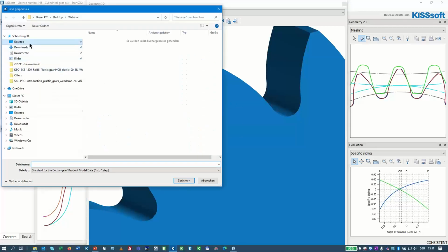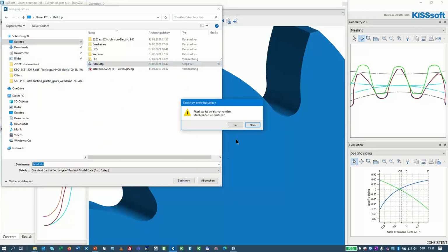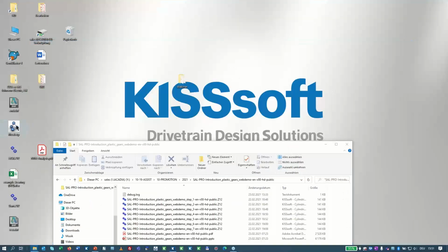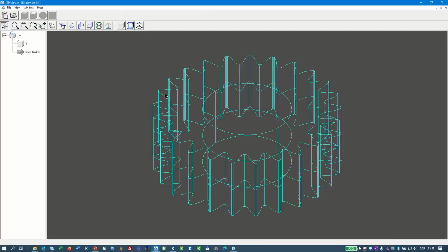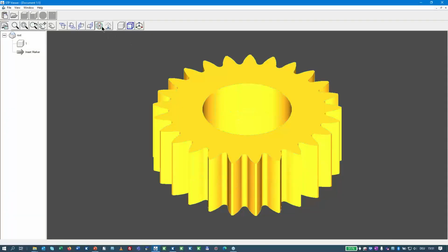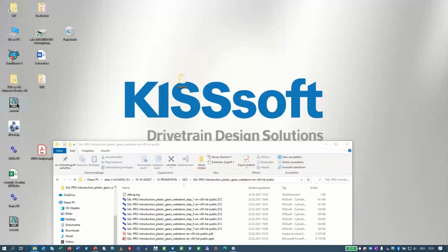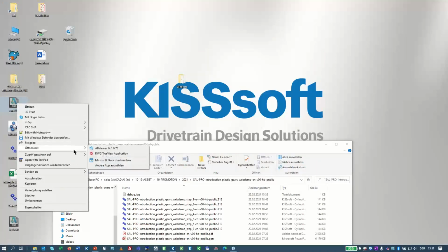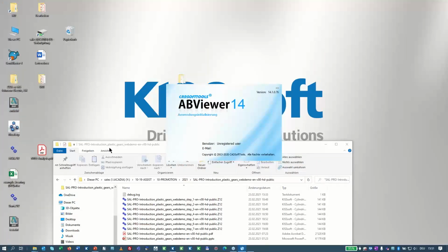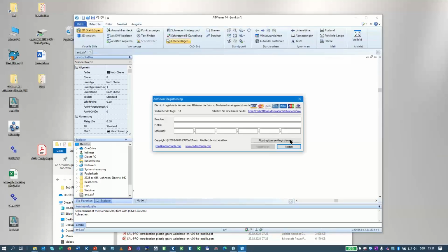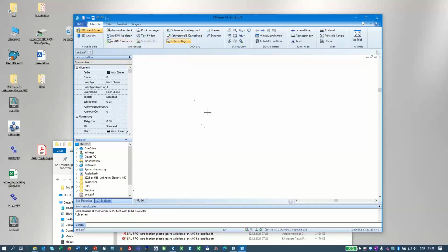Let me export this as well. And then I can proceed. I have here my shape as a 3D body. I can use this either in a CAD or in a CAM software as the basis for an accurate machining of the gear or the electrode. And of course, the same as a 2D shape. If I need a path to supply to the manufacturer,